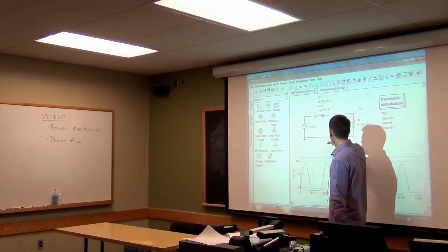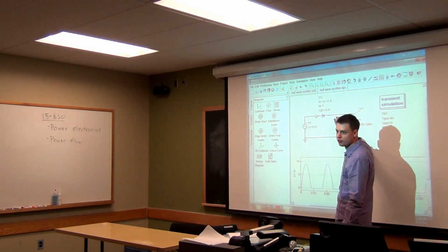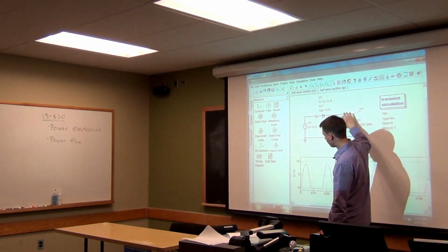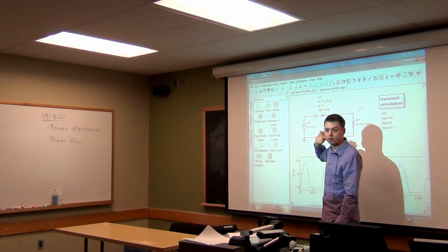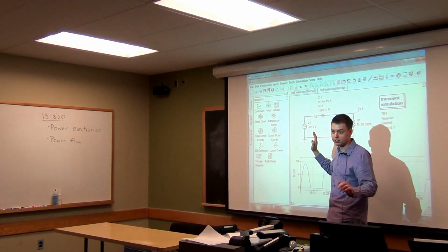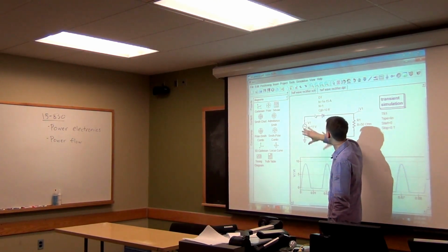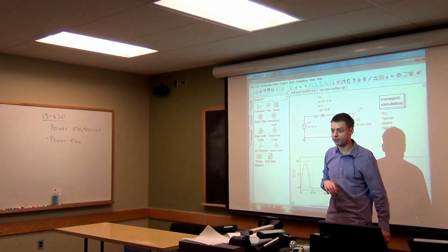Right? And right here, there's no capacitor, so it's not being smoothed at all. So it's just seeing only the voltage when it's positive like this. When it's negative, this looks like an open circuit there, so it's not seeing any difference across this bit here. Of course, there would be a difference across this bit, but across here, it's not seeing any difference.